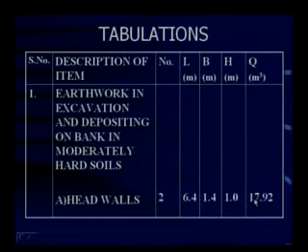So, how do you get the quantity, or in terms of volume? That is in meter cube, because for convenience all tabulations are being made in meters. As you know, L into B into H will give you the quantity. The quantity here is 17.92 cubic meters. Now, where else do you need to excavate? You have made the calculation of quantity under the head walls. The next item is like this.